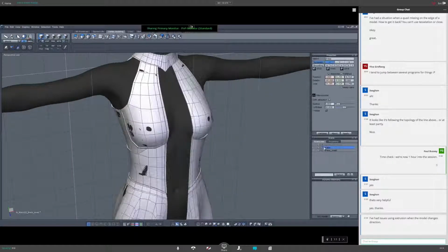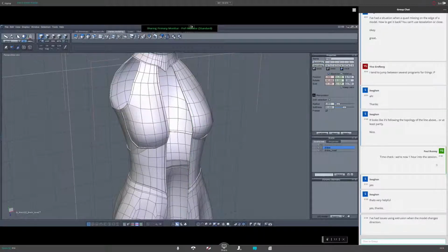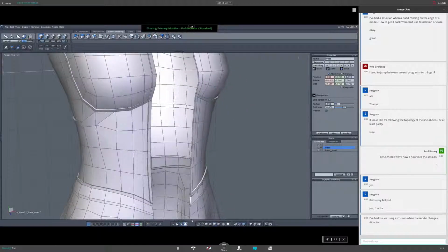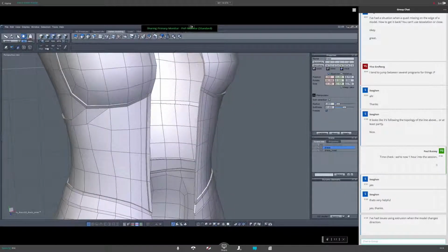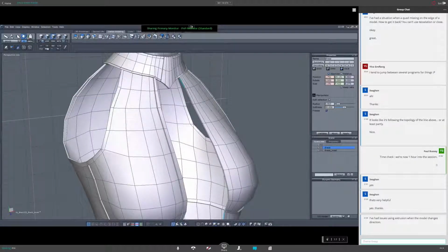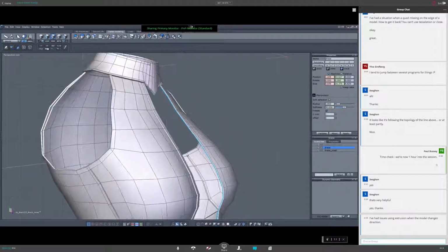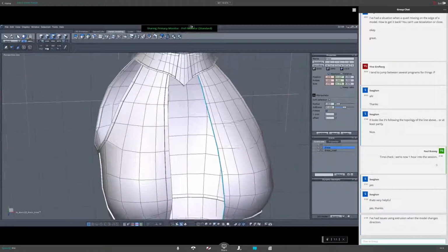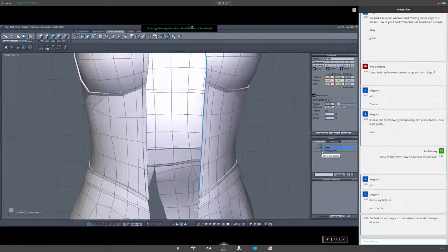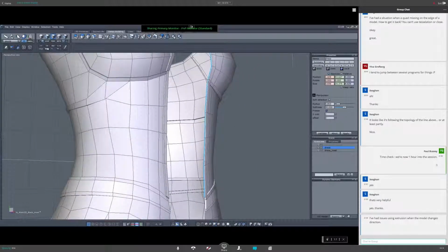And since this is a new technique, I'm going to show you in detail how this is done. First, I need a template to create such a shape, and it's always a good idea to use what you have. So we had all this work creating this dress, so I would say we are using this dress as our template. I'm selecting edges along the inner seam of this top region of the skirt because I want my inset to fit exactly into the skirt. So as you see, I missed a few.